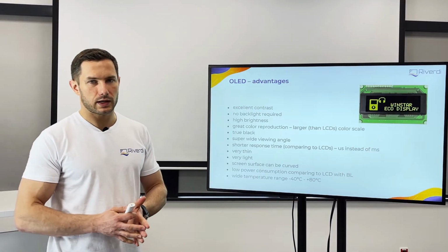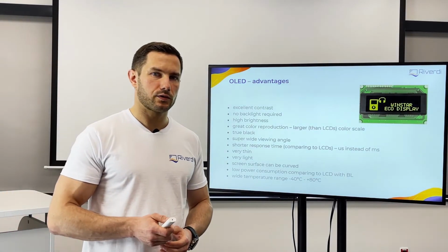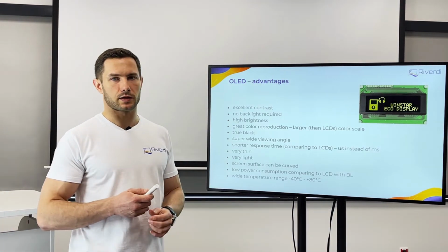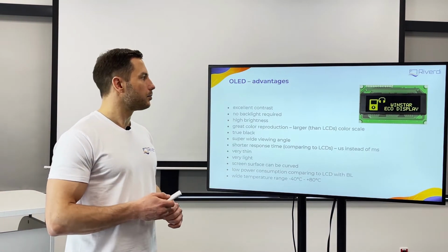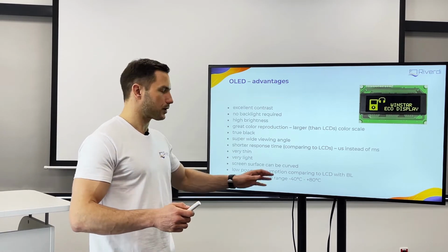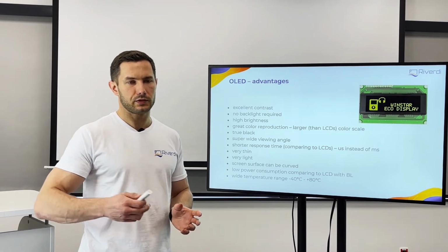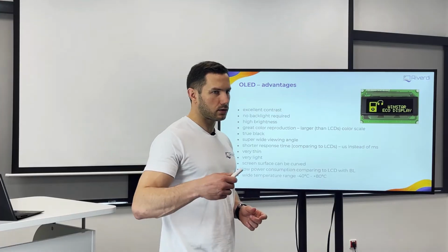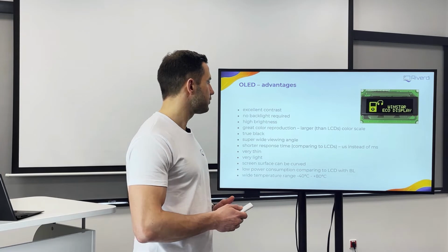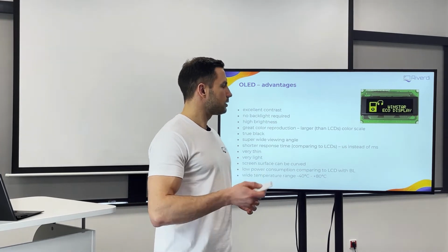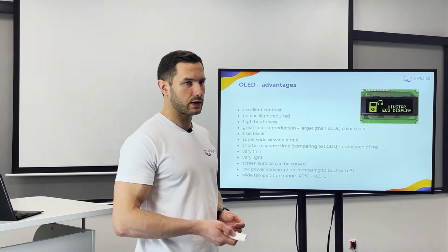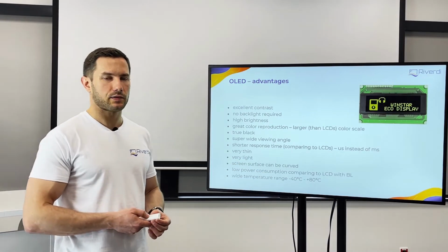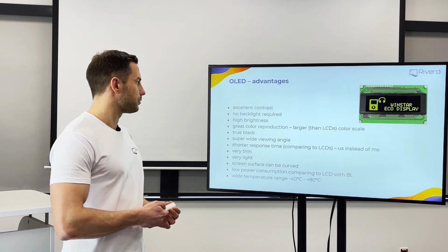On the other side, with high temperatures, you need to be careful, because it decreases OLED lifetime. So you need to check the spec and maybe contact manufacturers if you require high temperatures for your OLED. If it's for short periods, then it's fine. But if your OLED display needs to work constantly at a high temperature, let's say above 50, 60 or 80 degrees, then it's worth checking how it will affect the lifetime of an OLED display. It affects it more than a typical TFT.